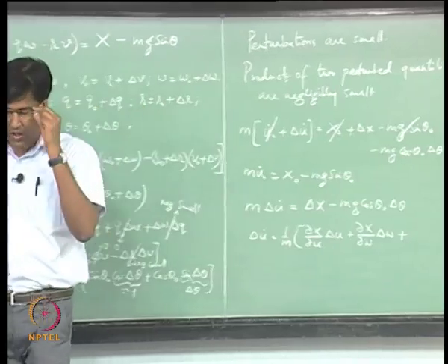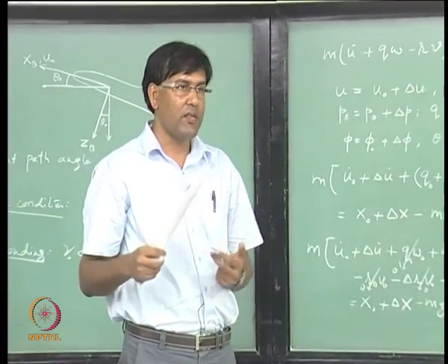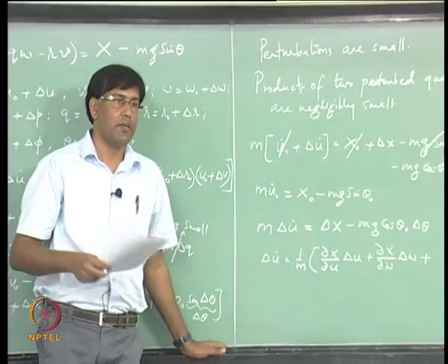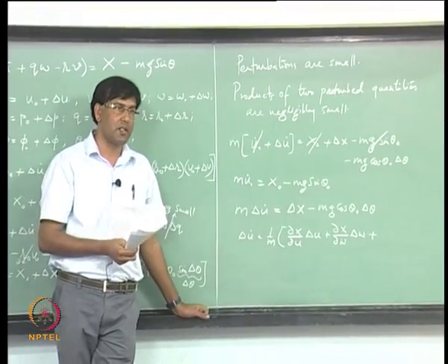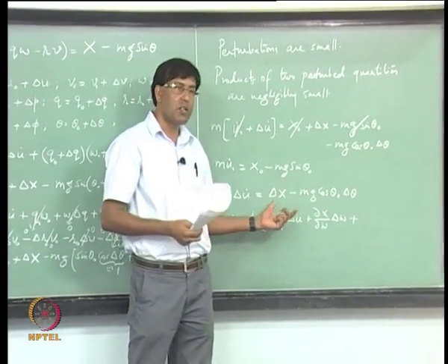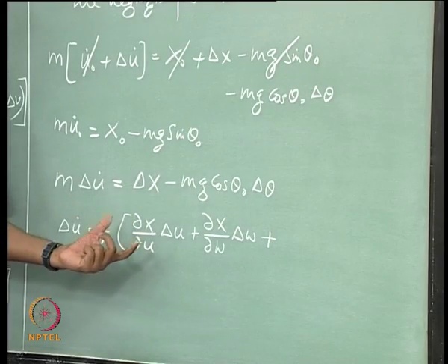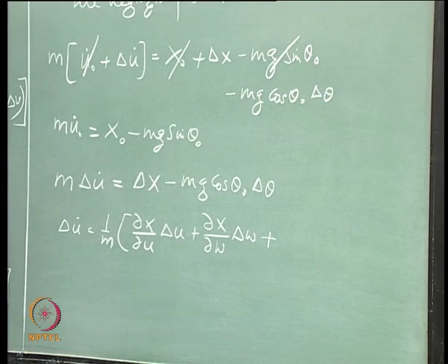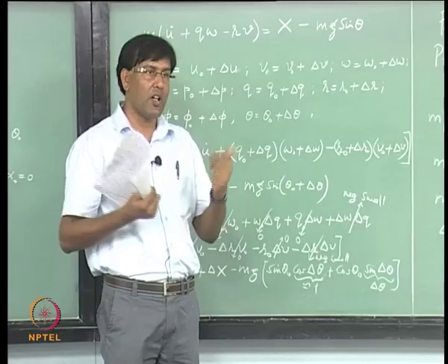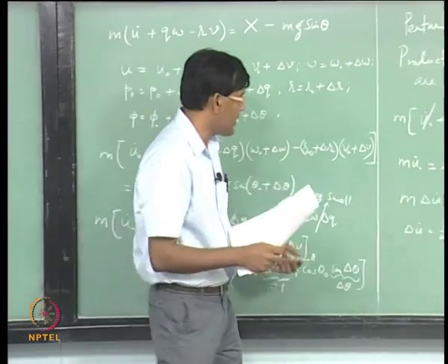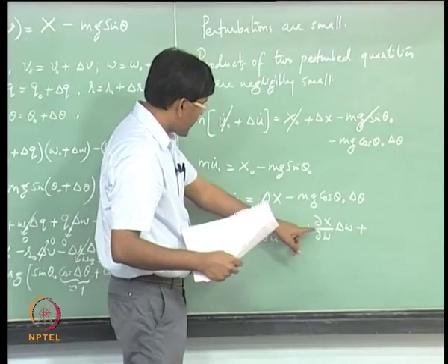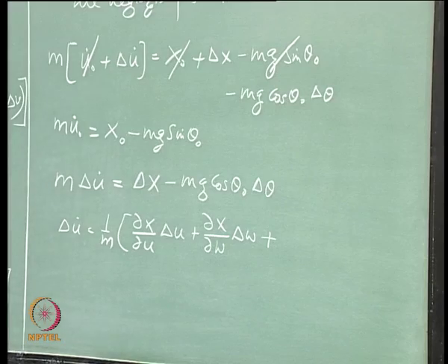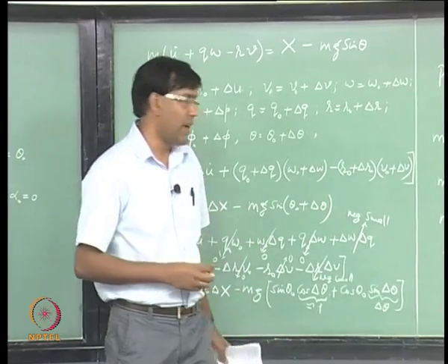In general, if you're talking about the post stall flight regime, then these forces are also going to be functions of many other non longitudinal variables, but we are talking about pre stall flights. This force is the sum of aerodynamic and propulsive forces along the body fixed axis. So it is not going to be a function of the non longitudinal variables in the pre stall flight regime.